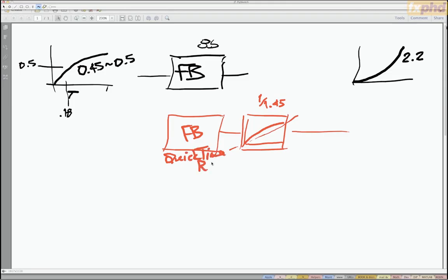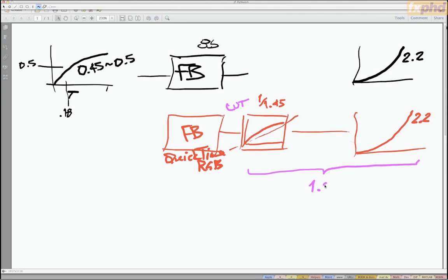So that's the historical output hardware path from an Apple frame buffer, and these would, of course, be QuickTime RGB values, out to the display, which did exactly what everyone else's display did, 2.2. You know, Apple never made displays that were wacky. It was just this LUT that was a little strange. So the combination of those two was equivalent to a 1.8 power function instead of a 2.2.